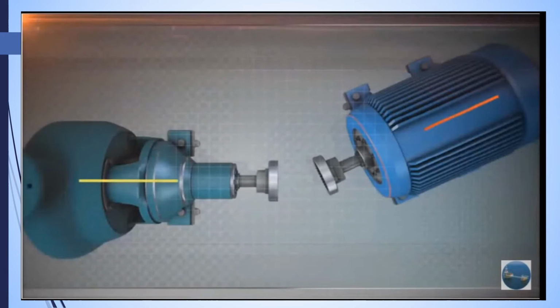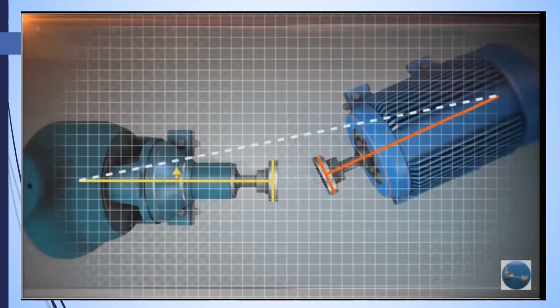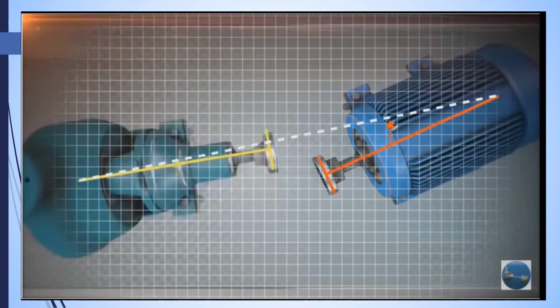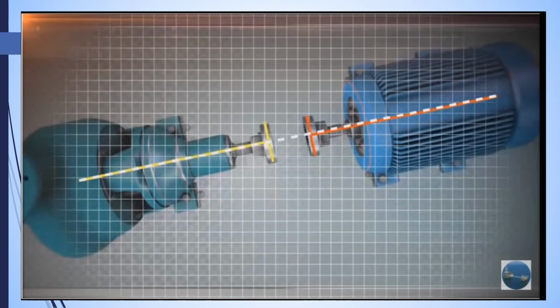or make an optimal move, which is usually the best option because it saves time and does not require working on the structural components of the machine or its base. An optimal move means making a small adjustment on the stationary machine to eliminate the need for the impossible move on the machine that originally became bolt-bound. We simply use the laser alignment system to show us the smallest correction. The same applies for the base-bound condition.